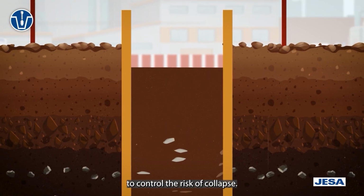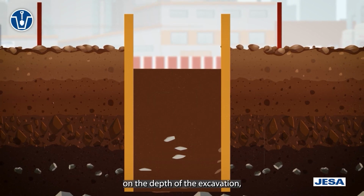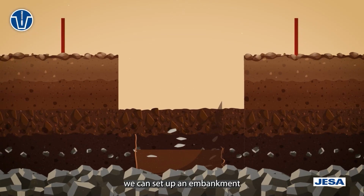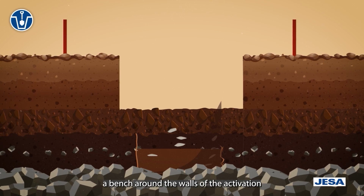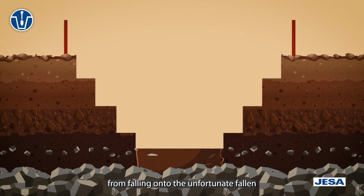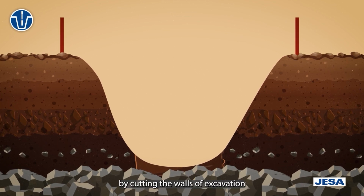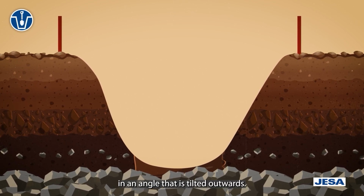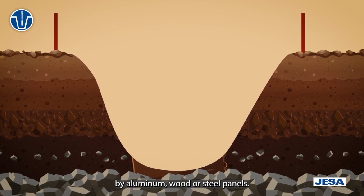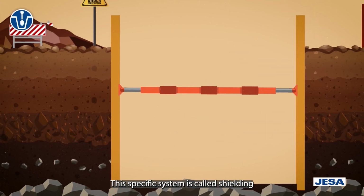To control the risk of collapse, there are different types of protection systems used depending on the depth of the excavation, the nature of the soil and other factors. For example, we can set up an embankment slope per bench around the walls of the excavation to prevent debris from falling onto the worker. We can also proceed by sloping, by cutting the walls of excavation in an angle that is tilted outwards. The sides of the trench are also supported by aluminium, wood or steel panels. This specific system is called shielding.